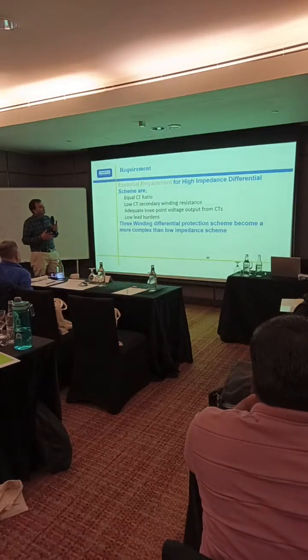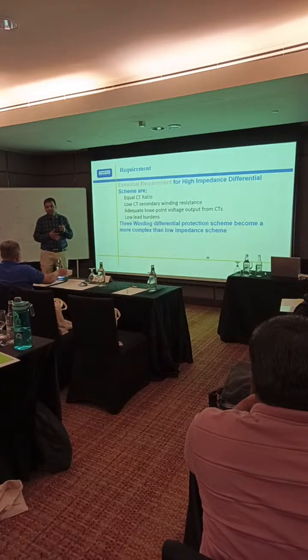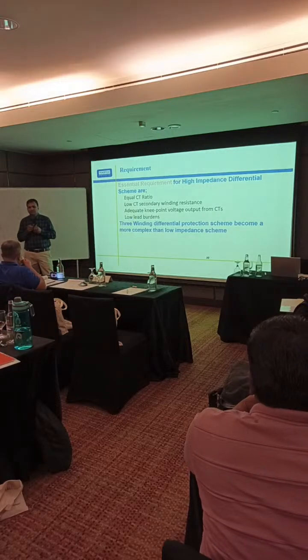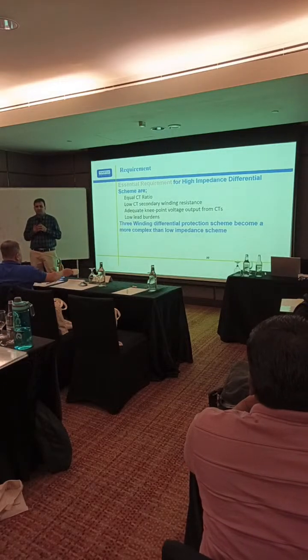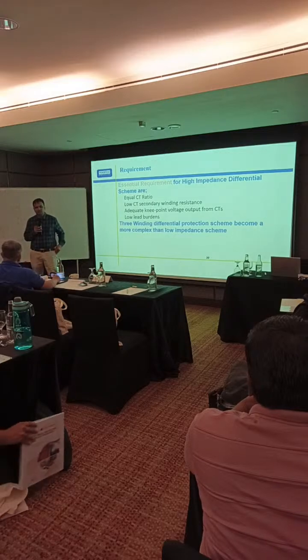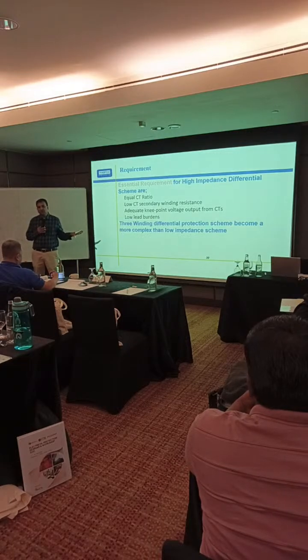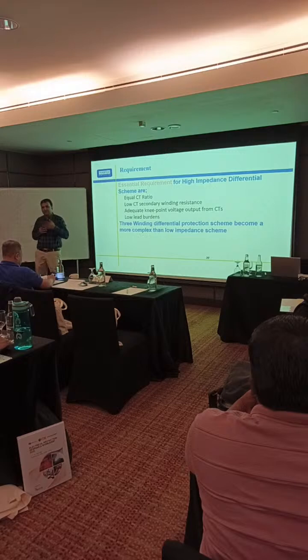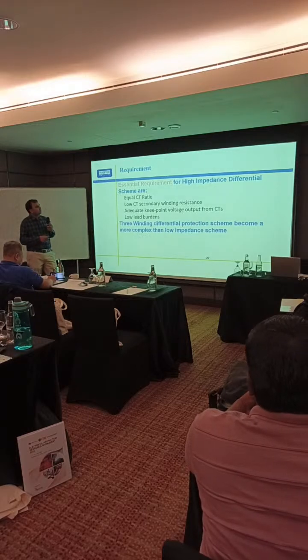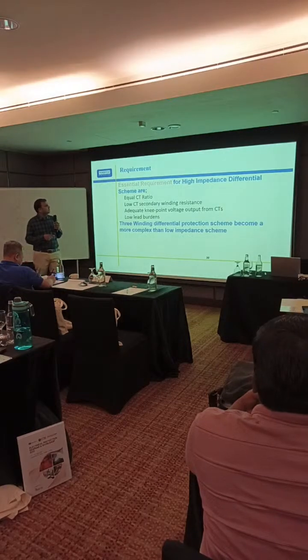That is why we move to low impedance differential rather than high impedance differential. You will not find much high impedance differential protection anywhere now. We only use REF, and why we use REF, he has already explained very well yesterday. So mostly we are not using high impedance differential now.